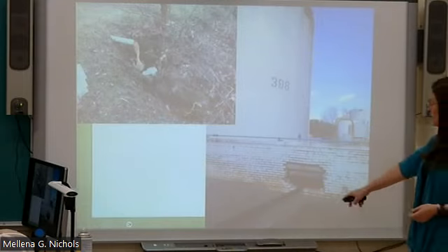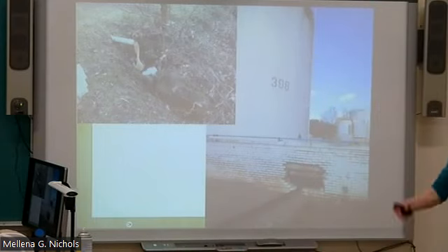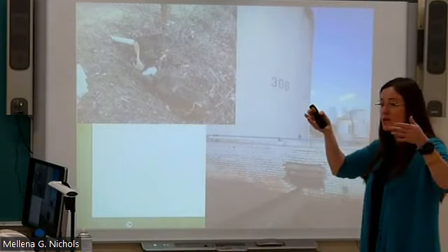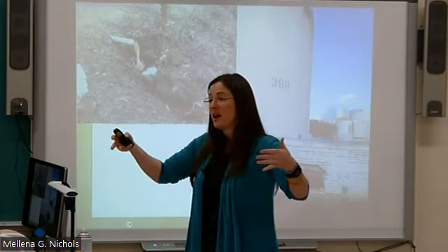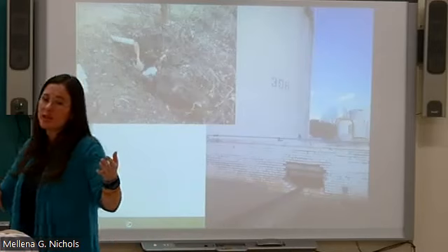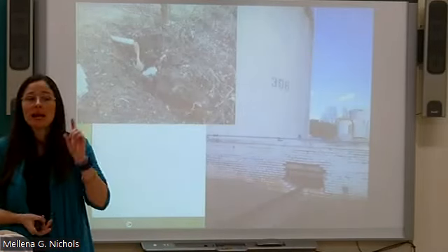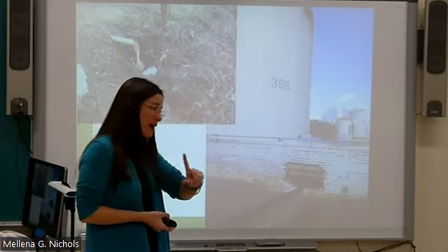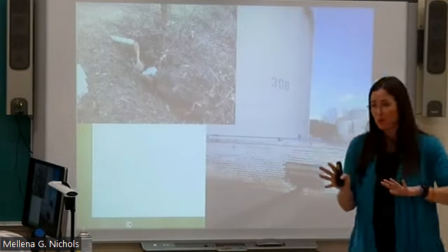And then you can see the surface down here is the gravel. We already talked about that, right? So typically when you think containment, you think watertight. It should hold the things that are in there. Yes, and that is what the standard requires. It's watertight and large enough to hold at least one of the containers you have, plus in most states, it's going to say 25%.